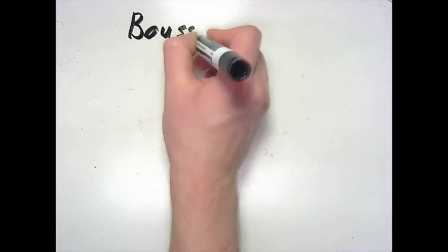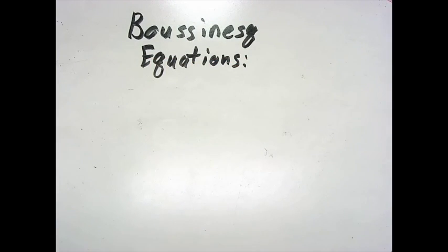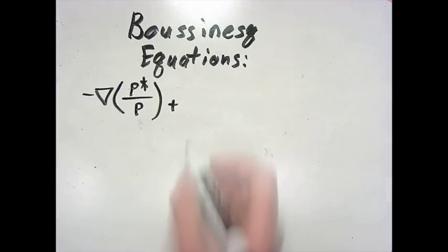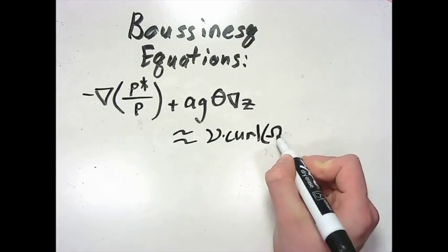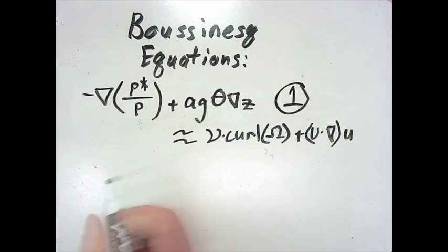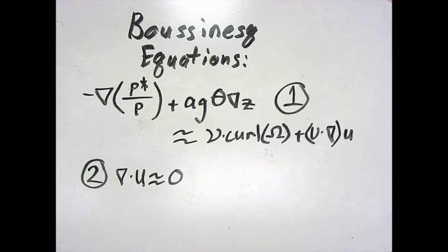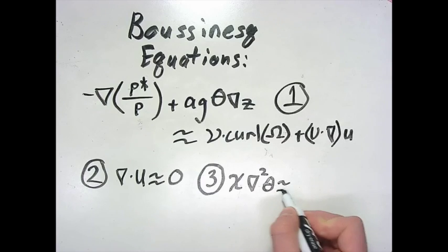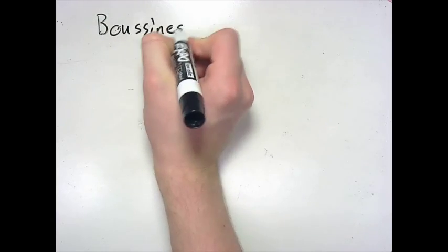And here we come to the Boussinesq equations. These have been adapted from our normal fluid equations to include the thermal presence. This first equation is the counterpart to the Navier-Stokes equation. The second is for a fluid of approximately uniform density. This third equation assumes constant thermal conductivity and describes the heat transfer per time into an element of fluid per volume.